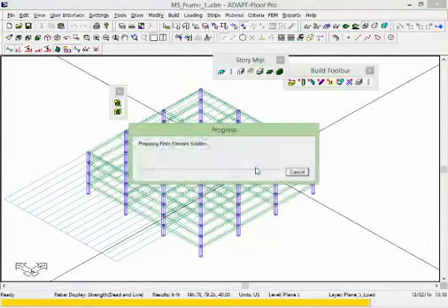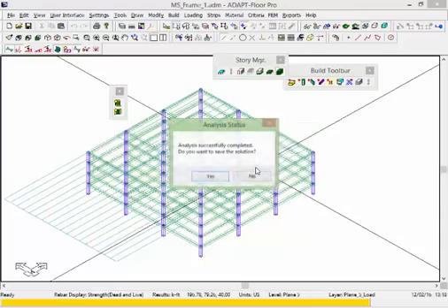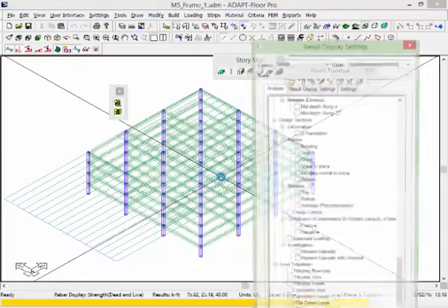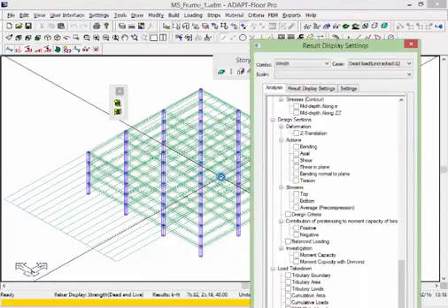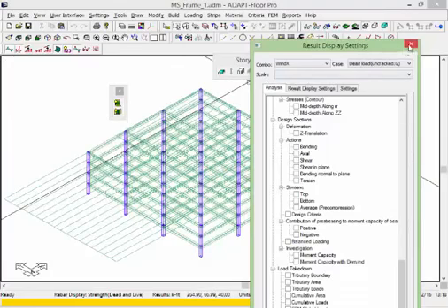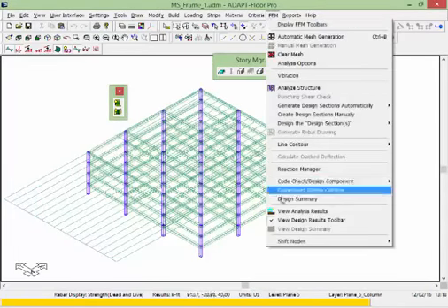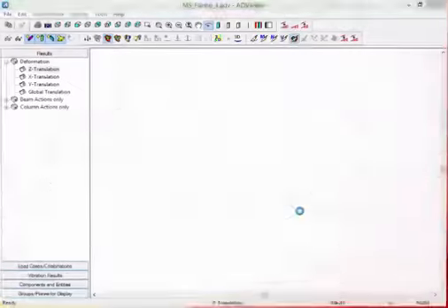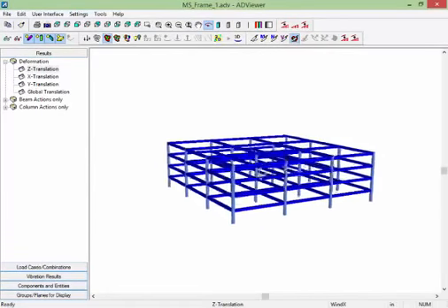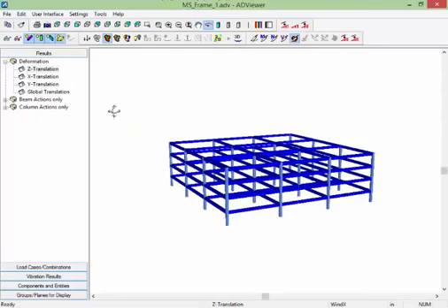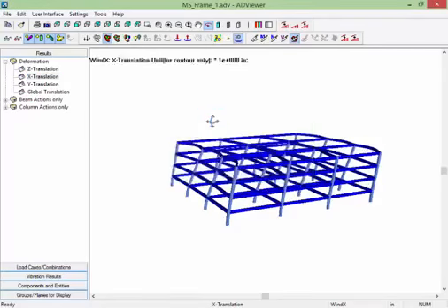And after we've analyzed that, we want to visually inspect the deformation of the frame relative to these loads, just to make sure that the frame is behaving, or it's deflecting the way we would expect. I'll go to FEM analysis, view analysis results. We have the frame shown in this module called Add Viewer, and I'm going to select the X direction translation, and I'll go up to 3D, and this now becomes the displacement of the frame.